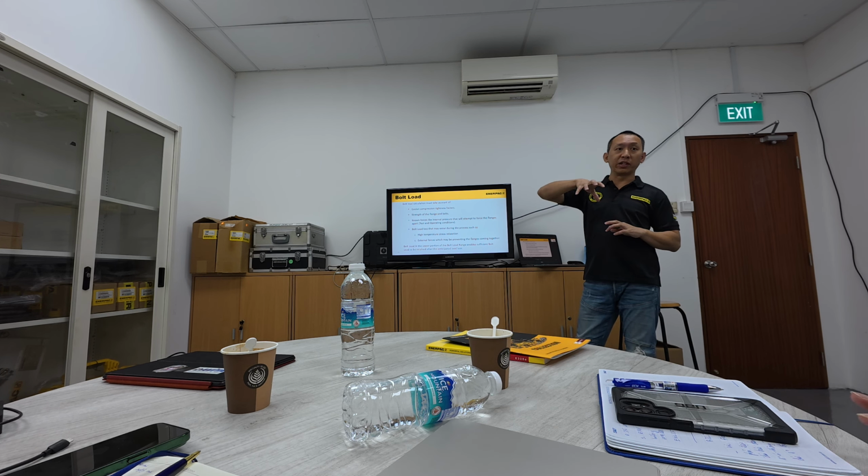For a hydraulic torque wrench, we can set the pressure of the pump. We can do a torque verification using a calibration system. We have a calibration cert, so based on that we can determine how much torque the wrench outputs.